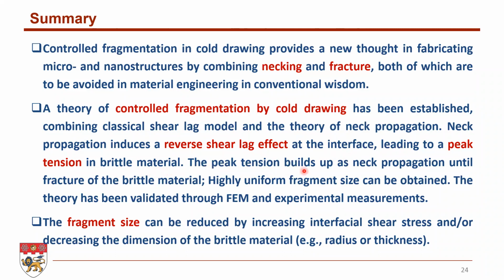The peak tension builds up as the neck propagates until fracture of the brittle material, and we can obtain a highly uniform fragment size. Our theory also suggests the fragment size can be reduced by increasing the interfacial shear stress and/or decreasing the dimension of the brittle material.